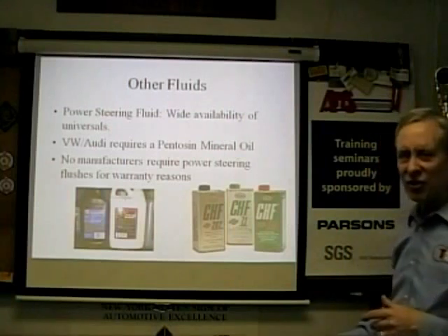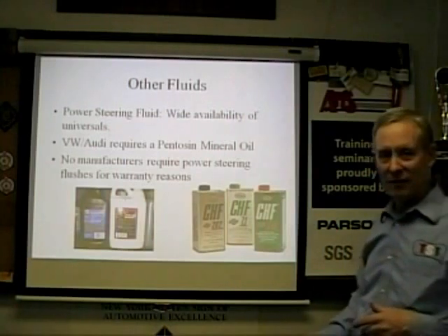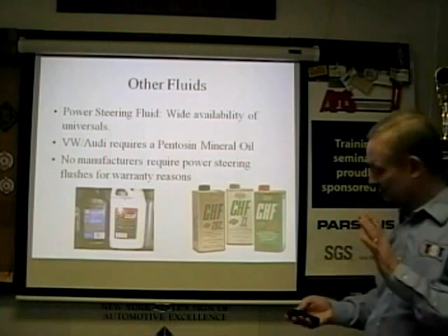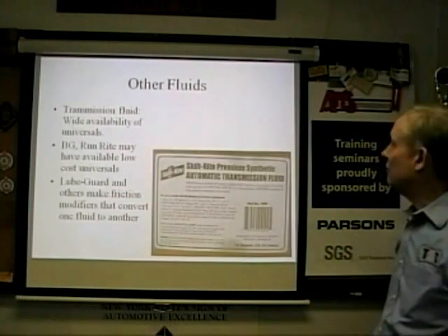Nothing's good for everything. Use your senses. If the fluid looks cooked or it smells, it is cooked. That's it. All right, transmission fluids.